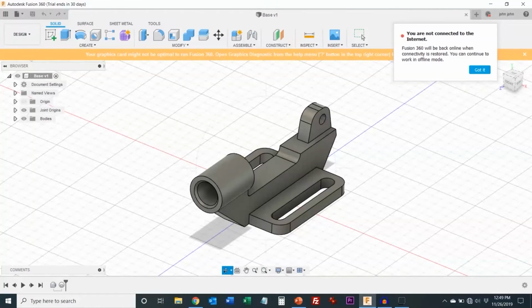Well, this adds a lot of complexity because now instead of just a simple mold with two halves and no moving parts, you've added moving parts to the mold. These side actions have to be pushed in and then pulled out, and this adds a lot of complexity to the mold, and molds are very expensive. So complexity equals more expense. Designing your product to require side actions can be a really expensive thing to do. In almost all cases, it's much better if you can design the product to not require side actions.